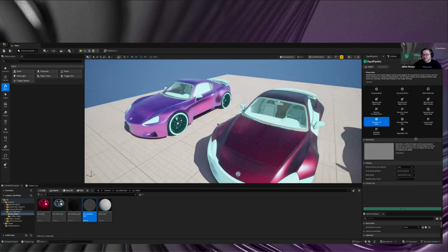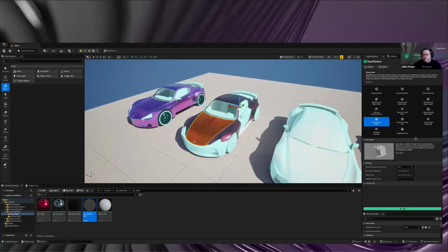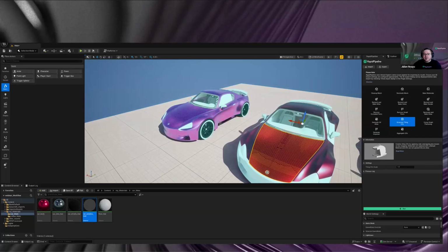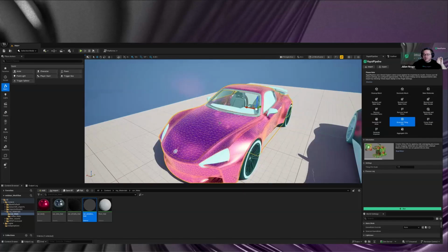Yeah, we also have tiling UVs. So that's maybe something interesting if you want to have some procedural material, which is definitely possible in Unreal for sure. That's something we can always generate. And these are basically box projected from 6 sides, and then they're basically overlapping. So they're not great for actual texturing, like throwing a texture map on it, but they're amazing for procedural materials. You can try that out.